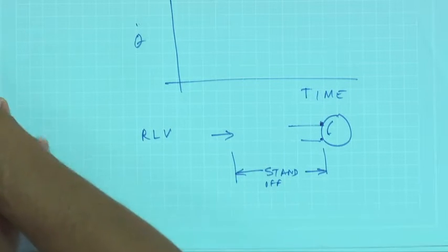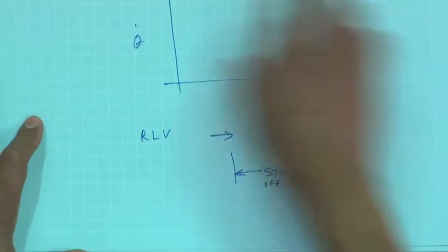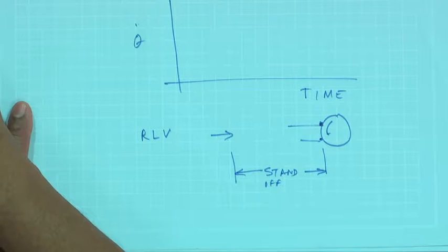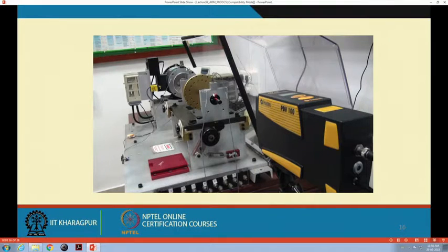And in fact, this is a linear laser vibrometer in the laboratory, wherein we are shooting the laser beam onto the outer edge of the bearing. Imagine, in traditional vibration monitoring, I put an accelerometer on the housing, but if I have a laser beam, I can focus it on a very small point and measure the vibration, and this is what is being done in the present setup.